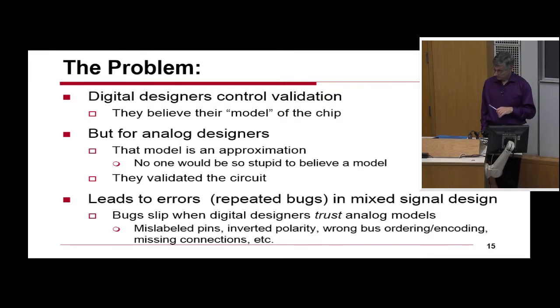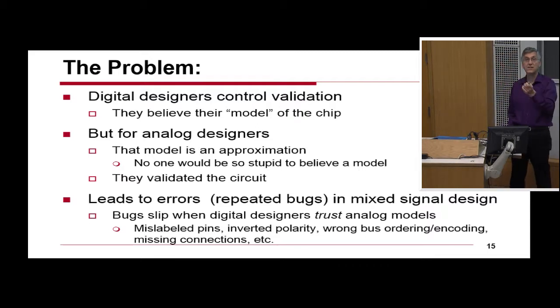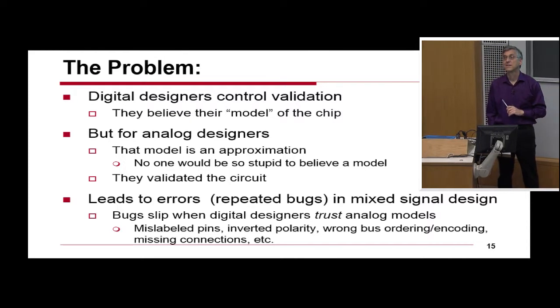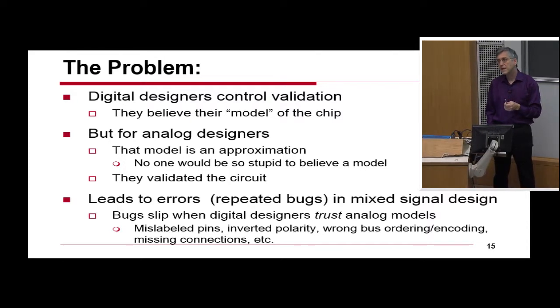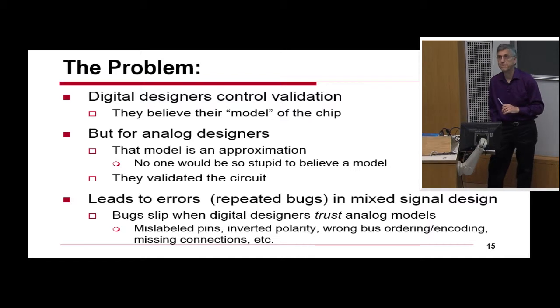But the system doesn't work because there's some inverter gates someplace screwed up, or there's a polarity inversion in the overall system, so the digital can't actually control the analog like it was supposed to, right? And those problems arise because the model didn't correspond to the actual implementation that was used for the top-level validation. Or even worse, the top-level validation wasn't done.